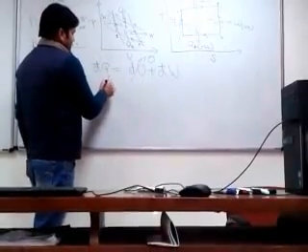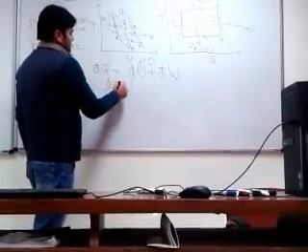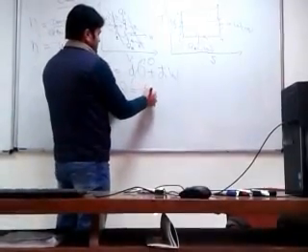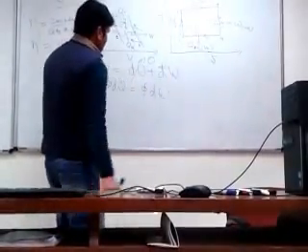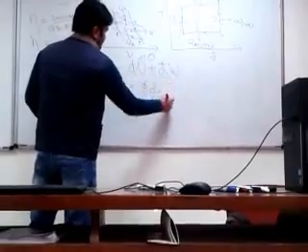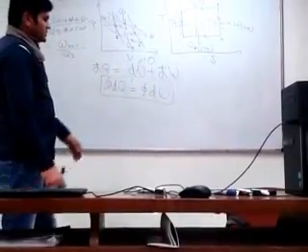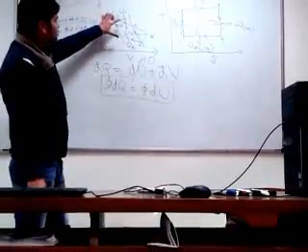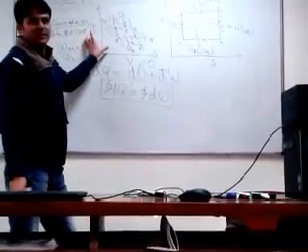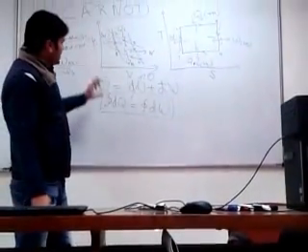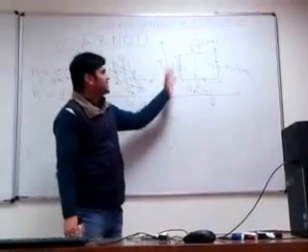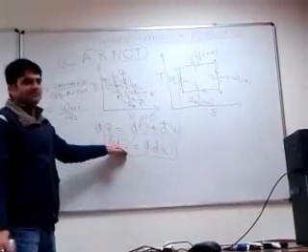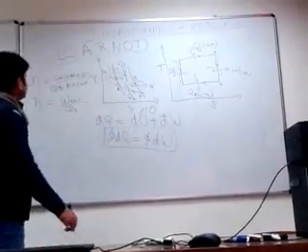So for a cycle, heat transfer is equal to the work transfer. As we know, the area enclosed by the processes on the PV diagram gives you work, and the area enclosed by the processes on the TS diagram will give you heat transfer. So we can write that.